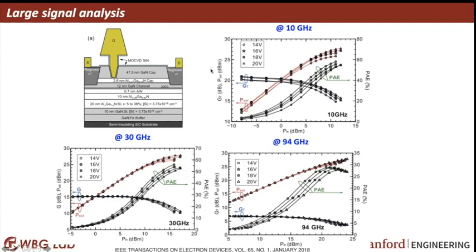And then sometimes, for example, here at 94 gigahertz, the maximum efficiency attained is only 30%. Then you need to talk to the materials students or materials researchers to come up with a better mobility. That's how the cycle happens. The materials engineers give us these materials, we fabricate the devices as I explained in the previous slides, and then we do these characterization techniques.